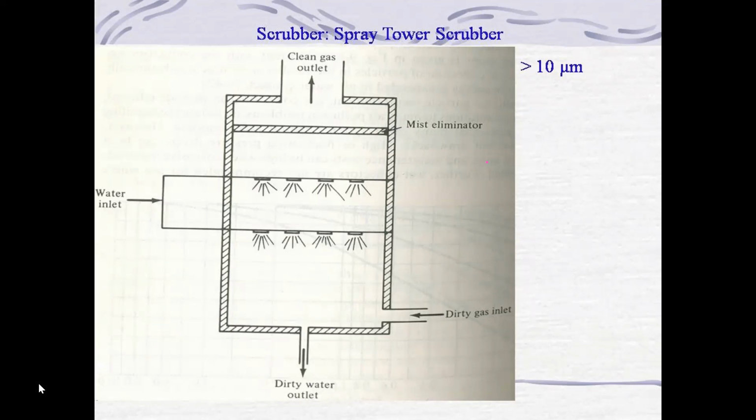Have you finished? Scrubber. What is meant by the scrubber? Scrubbers are applicable for wet gas, meaning when small particles of water droplets are present. In that case, the earlier two, the cyclonic separator and settling chamber, will not work. Both the cyclonic separator and settling chamber are for dry gases and for the removal of particulate matter.